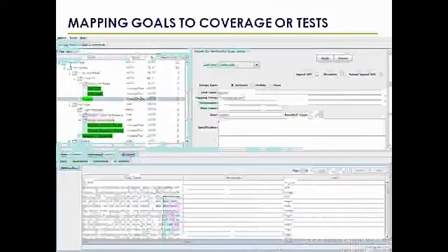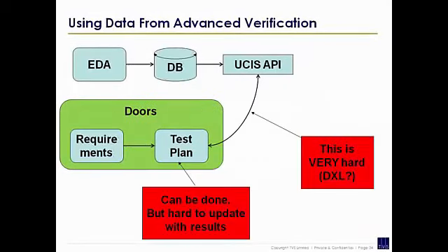Okay. So going back to the difficulty with using these advanced verification techniques, as the gentleman said, what you can do is take your requirements and map them. So you break down the requirements, and this is the requirements tree. Then in your test plan, you say I'm going to write directed test 1, directed test 2 here, and directed test 1 and directed test 2 here. Then you run those tests over in your simulator, maybe it's the Xilinx simulator, and then you look at the results of those.